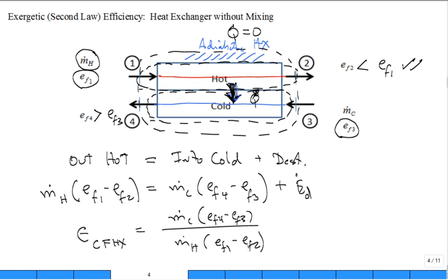You just know that heat exchangers often are an area where the design engineer wants to improve and has an opportunity to improve the efficiency of the overall system. Basically, make small delta T's. Small delta T's to drive the same Q dot. And so you can minimize it, that's going to help with efficiency.